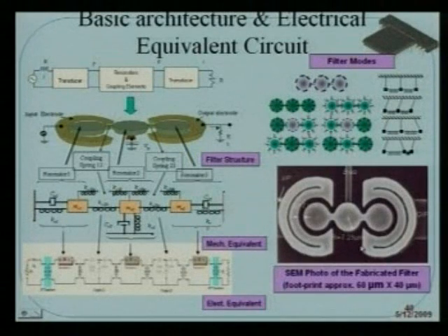Very recently, this is a very interesting work, people are trying to develop new concepts in RF design. Say I want to design a filter, for example for a GSM band, frequency 915 megahertz and bandwidth 26 megahertz. Then you need some sort of an inverse Chebyshev filter of 7th order or 3rd order, depending upon the kind of roll off you want. You have a number of components, L and C and R, it's pretty high, and it requires a lot of area in the silicon. But by using the MEMS technique, micro electromechanical systems, you can reduce the area.